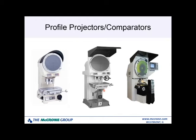You can have two different types of illumination: transmitted light illumination that comes from beneath the specimen, or reflected light illumination that comes down and shoots light on the surface of the specimen. When light comes up from beneath the specimen, it provides a profile of the part that you're looking at, and this is where you would make your measurements.